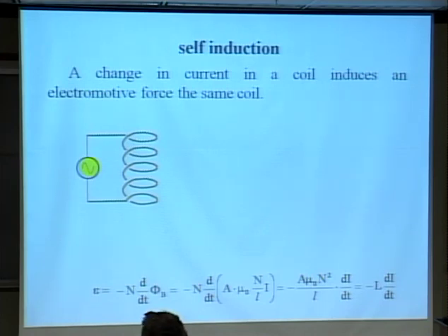In practical cases, if the frequency of the current which we run through that coil is high, then resistance makes a small contribution to the impedance of this element. A real inductor behaves like an ideal inductor connected with a resistor in series.